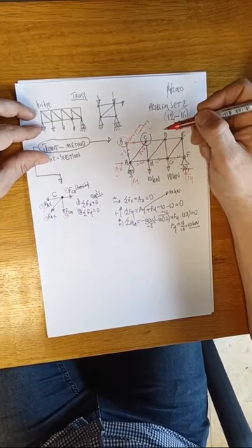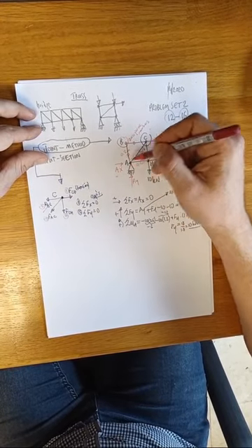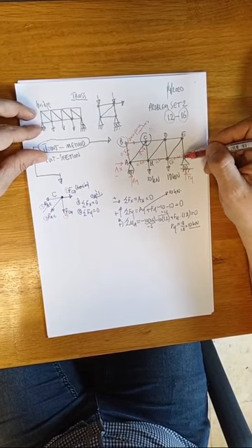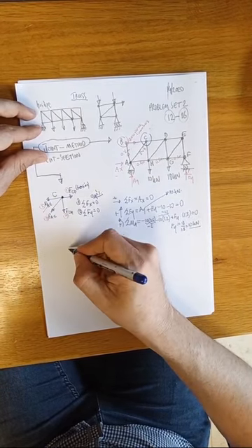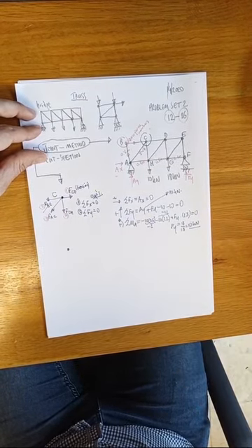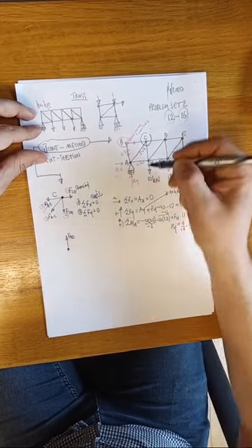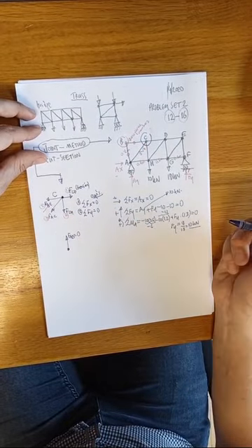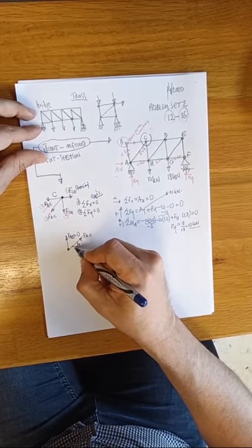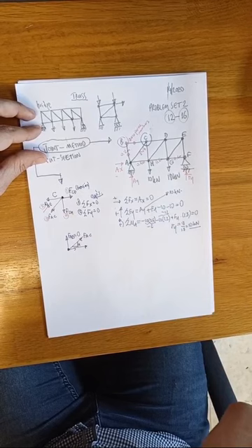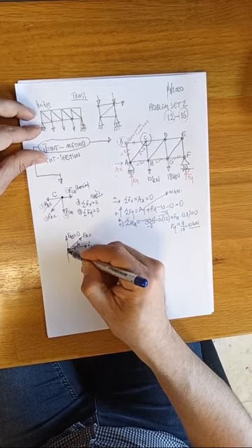So start from another point. Maybe it would be better to start from A point here, as you see, or the F point, as you see. These are good points to start with. For example, starting from A point, what you will see? Let's see from A point. A is an easy one. This is FAB, which I found as 0 force member. It is 0. The other one, FAC. Also draw the triangle like this. The other one, what is this? FAH. Okay, and there is the reaction here, AY.